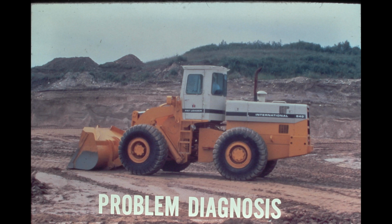If possible, the machine should be operated by the service person to check all of the hydraulic circuits on the machine. If only one circuit is found to have a problem, then any component which affects more than one circuit is not the faulty component.